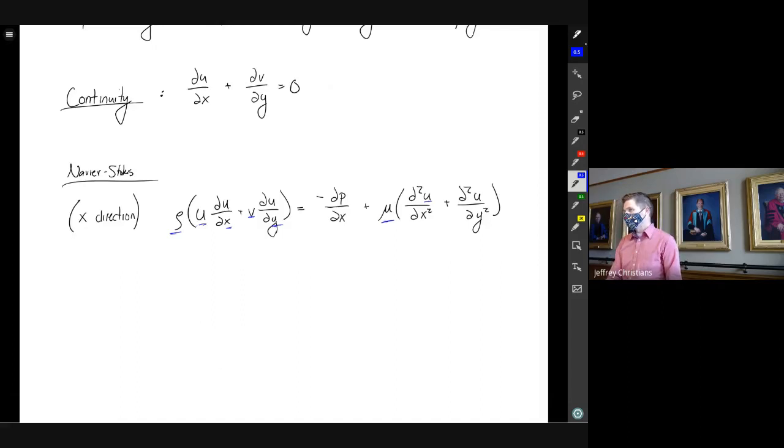Okay, pressure, that was one thing we didn't actually look at, but pressure might also be important. We see a P show up there. Okay, so let's do 10 more experiments at 10 different pressures. All right, things can very quickly get lots of fun. What we're going to do is try to simplify this down and condense it down so that we don't have all of these separate things. And we're going to do that by non-dimensionalizing.